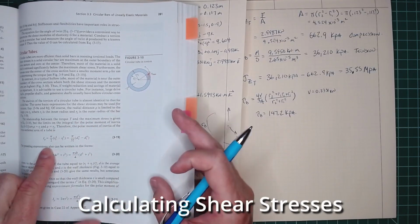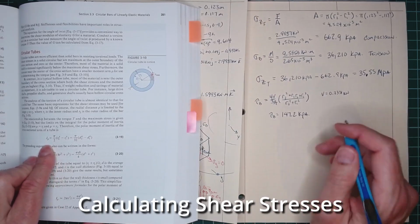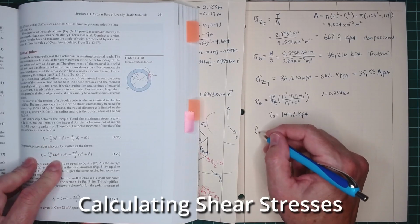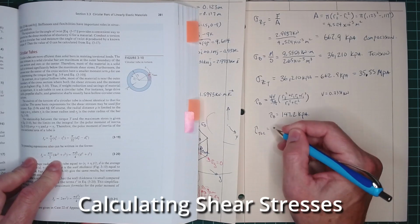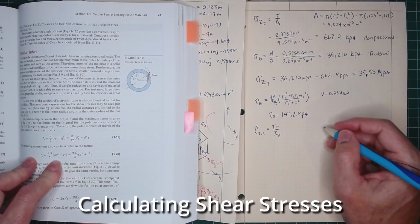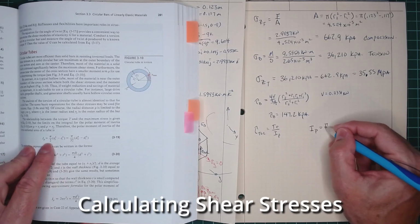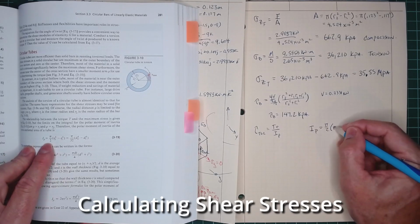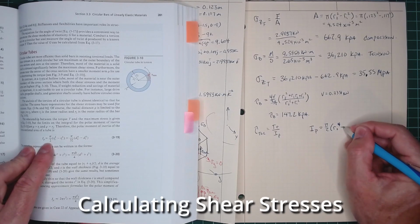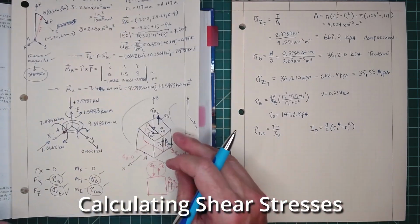We also have it listed here. So the shear due to torsion is equal to TR over IP, and IP is going to be equal to pi over 2 times R2 to the fourth minus R1 to the fourth.